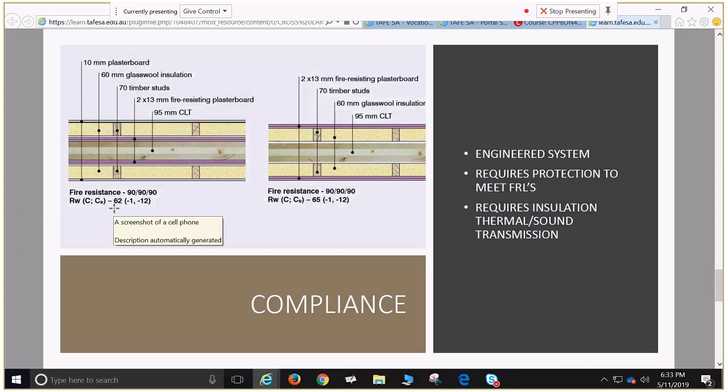That'll be the thing, I guess. Compare it thickness for thickness with concrete. Well, concrete's got very poor sound insulation, is what I worked out, which is actually my experience. But I know that people take it to be a great sound insulation, but it's actually not. It's really bad sound insulation. Where it performs well is in impact sound, in comparison to lighter framing, which tends to vibrate more and act like a drum.